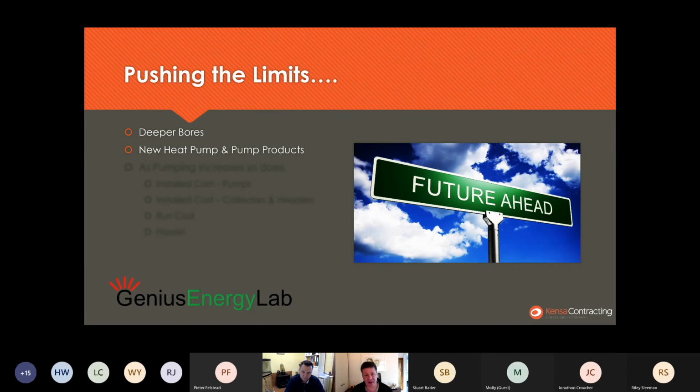Pump products, I can't remember if I mentioned this earlier, so forgive me if I'm repeating myself, but when I first came into it, to get a pump to deal with 110 kPa and stay within the 3% limit was quite challenging. But now we can go to 300 kPa relatively easily with modern pump products because the efficiency improvements and the product development in pumping have been so important. So pump products can help or hinder depending on how you see it.